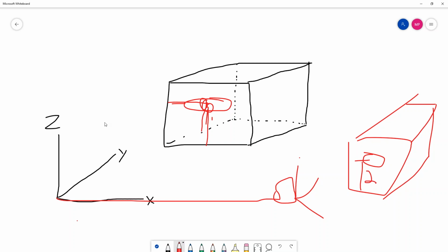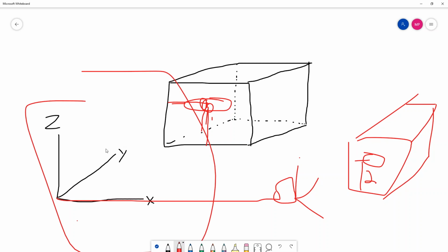So if you set your coordinate system to start, you'll be good. But as soon as you start shifting it around, you're shifting everything about that toolpath. So you'll change levels, you'll change locations. If we're doing a toolpath over here, now on this new cube, this is probably way out in space. So always confirm that coordinate system up front. Like Kevin says, you have the ability to change it. You can change locations, even change orientations. But just remember that that's going to fundamentally change the reference points of all your geometries, your toolpaths, offsets. A lot of stuff can be upset by the change of a coordinate system.